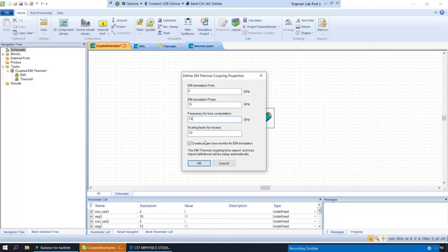This can get a little bit tricky, and again, I'll explain using the scaling factor appropriately to effectively model what your signal generator is doing. And again, this goes into why you might use the transient solver or the frequency domain solver, depending on what kind of excitation signal and what kind of source is generating that excitation signal. We're just going to leave this at 1 for now, though.